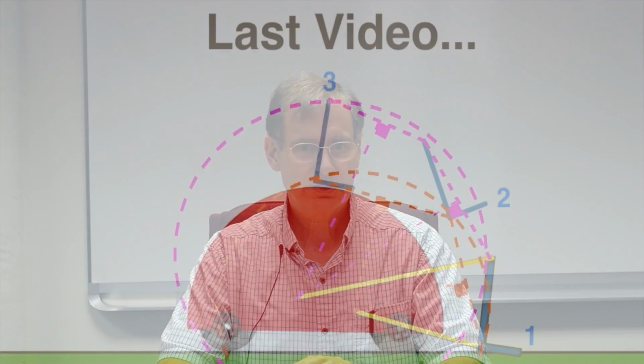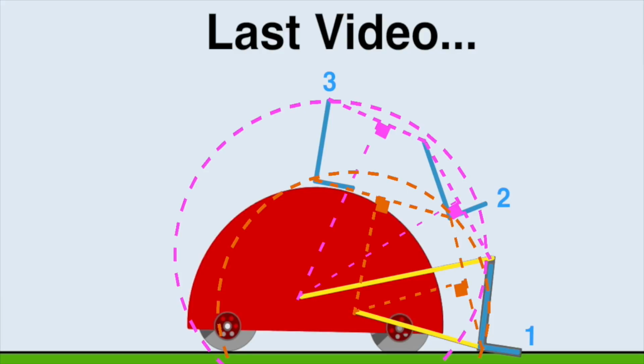So in other words, not rotate at all, but be able to translate either up, down, left, right, back, forth, or they could be in complex motion, where they were both rotating and translating, which is normally the kind of motion that a coupler in the linkage executes. So we looked at some position synthesis using a graphical technique that allowed us to determine the pivot points and the lengths of the links to achieve a certain position and orientation of the coupler.